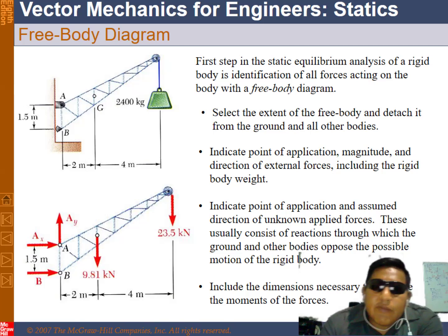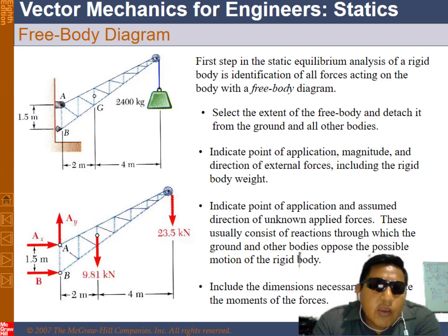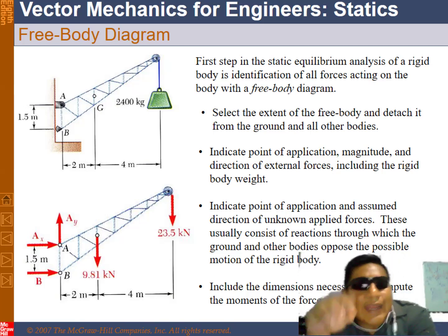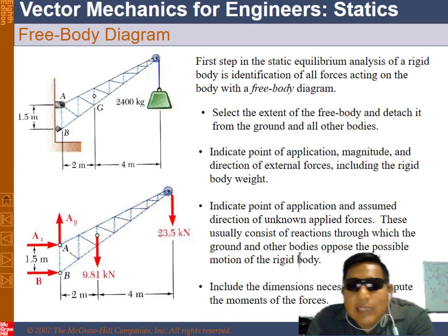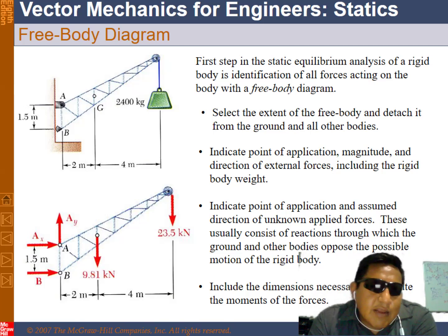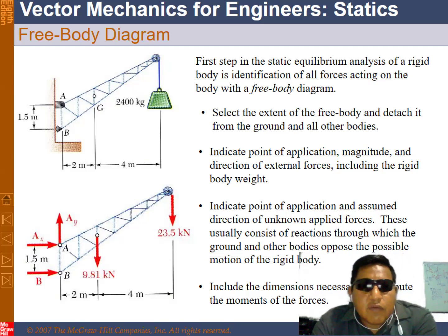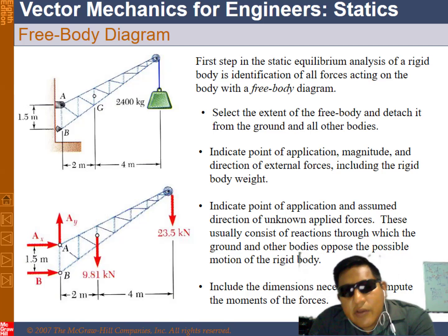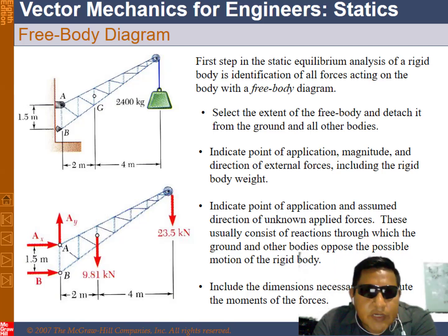You can check the figure or the picture. You have two supports, letter A and letter B. It's very important. At letter A, you have two reaction forces, a force in x and a force in y, since it's two-dimensional. And at letter B there is only one reaction force, at one point, not two reactions, only one.